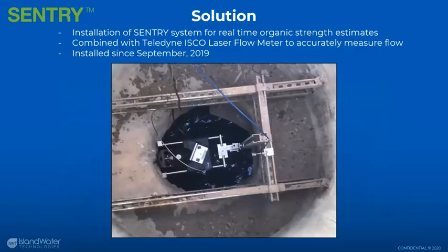This is a picture of the laser flow meter that is upstream. They've standardized on this particular flow meter because it's a billing application flow meter. And again, once this is installed, you can remove it without having to do a confined space entry. So the key to our sites is trying to keep them as minimally requiring maintenance as possible.